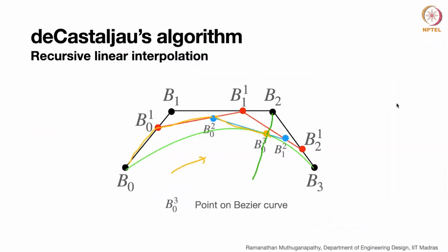Okay, and the other control polygon will come from here. Okay, this one and this one and this one. Remember, this is a degree 3 curve. We are splitting the same degree 3 curve, and you see there are 4 control points for this side of the curve, and then there are 4 control points coming from this side.